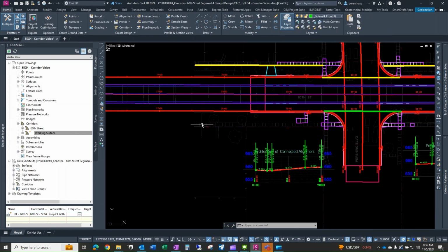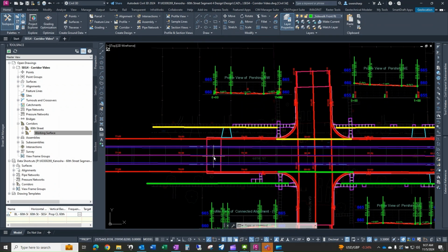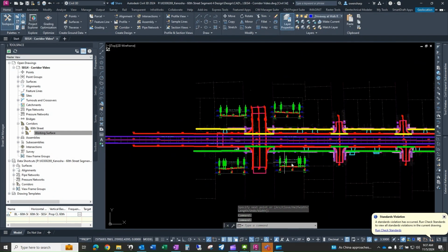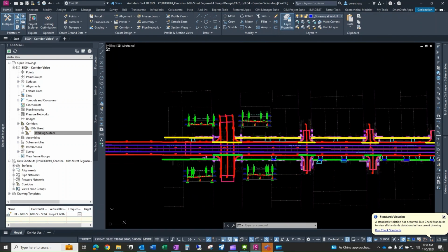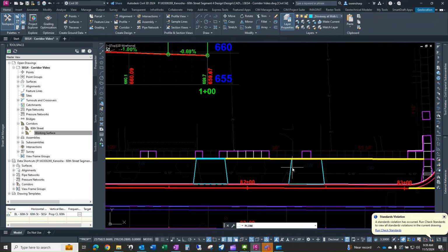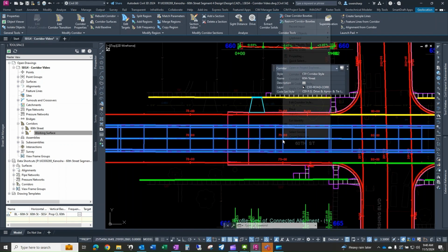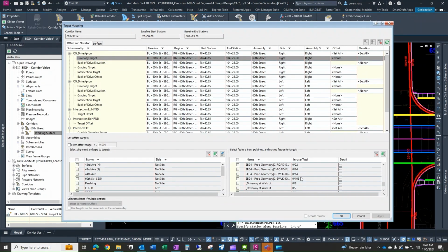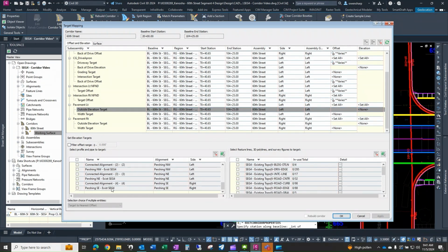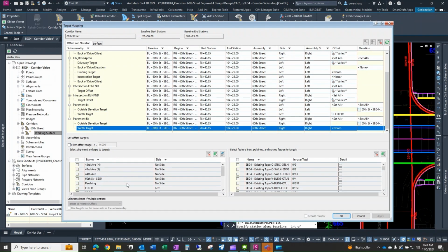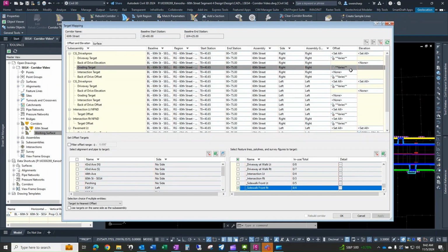Here we're drawing polylines for our custom sub-assemblies that we created with Sub-Assembly Composer. We set the targets for the custom sub-assembly once the lines are created. Once all the targets are set, then our corridor will know where to place driveways, where to drop off curb for intersections, and where the existing sidewalk is so we can tie in at the face of the walk.